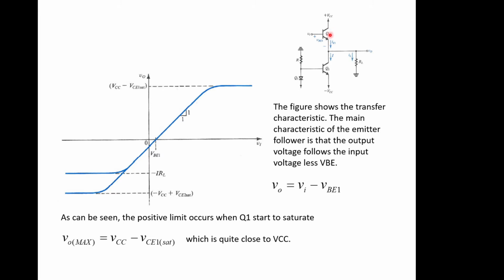This is as small as it can be because this is driving the biggest current it can, and all the current then will be two lots. There'll be some current coming down here. Some of it will go down here, and some of it will drive the load. And that's in this part of the characteristic here. But remember, we've got to have 0.7 of a volt positive in this before this transistor starts to conduct, so we get a slight offset, and that's what leads to some of this crossover distortion going forward.